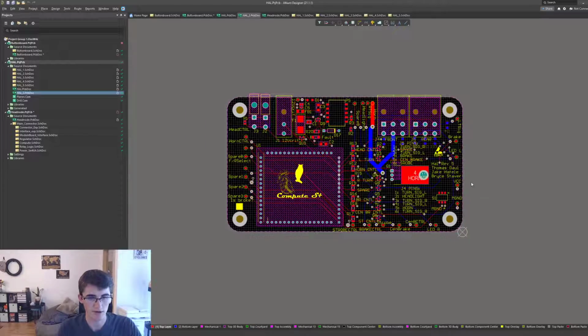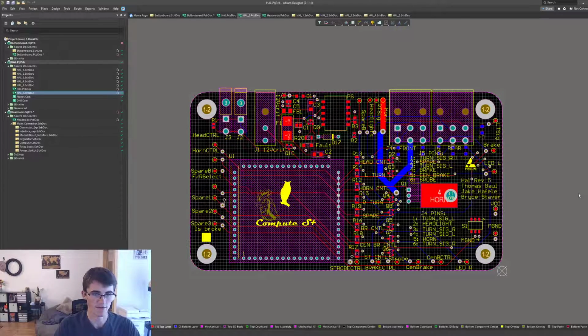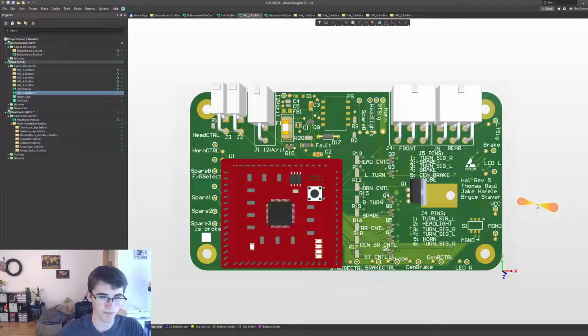Yes. So here's an example of the board we did to fix the horn issue when it broke. This happened right when we implemented this board about a summer ago, when we first put the board in. And what happened was, we had to add in this giant MOSFET because these MOSFETs right here were not equipped to handle 3 amps of current. We smelled it and it bubbled when we tried to turn the horn on. So this was an old version of the board. This is what we had for race 1 year.